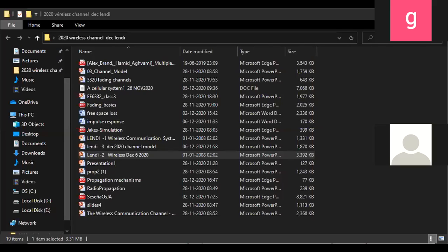varies in different ways because of the two, mainly it varies with the two factors: difference in the attenuations, one factor, and other one is the difference in the time delays. How I have classified them into four types: difference in the variations of the attenuation, difference in the variation of the time delay, and we have seen the most significant, the worst situation of the multipath effect. We have seen it when the attenuation is zero.